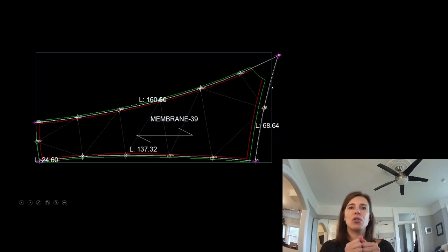So they stretch these out into their final shape. And it has to be very precise. Like, there are real calculations that go into this being able to stretch millimeters. How much would you have suggested one of these panels stretch? Roughly 1%. So on a 9-meter panel, 90 millimeters. That's a lot. That's almost 4 inches that we're talking about stretching that panel of fabric.